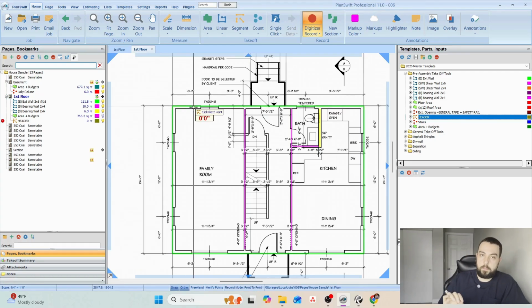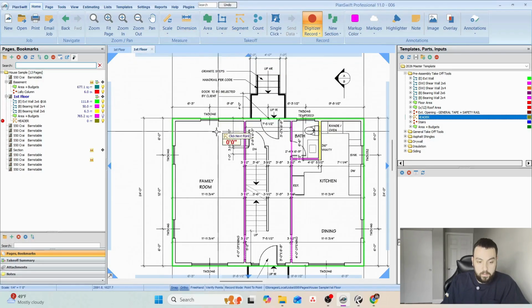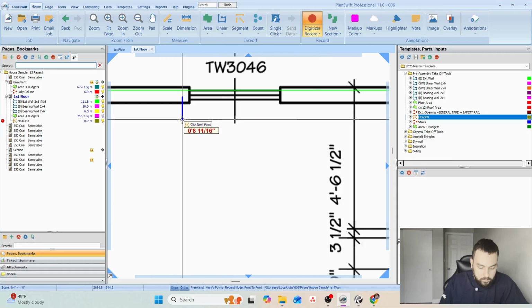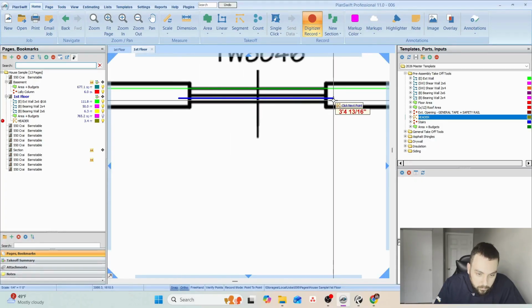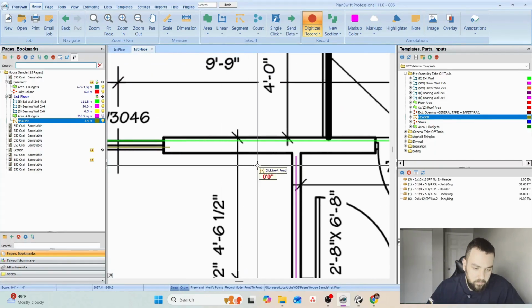If I see something bigger than 5, I'll just stop instead of checking every single one. I don't take off exactly the window. I just go a little bit over to play on the safe side, because the header is not the window opening itself, it's slightly bigger. I'm just playing safe here.